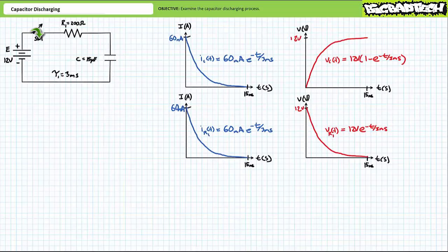After 5 time constants, in this case 15 milliseconds, the transient capacitor charging process is ended, and we have entered steady state final conditions. Voltage across the fully charged capacitor will be 12 volts, and current flow will have ceased. If switch 1 remained closed beyond 15 milliseconds, really nothing more would happen whether you kept it closed for an additional 15 milliseconds, an additional 15 seconds, an additional 15 minutes, or an additional 15 years.